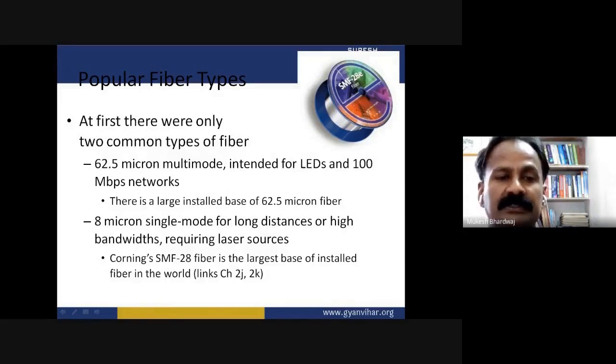There is a large installed base of 62.5 micron fiber. And 8 micron single mode for long distance or high bandwidths requiring laser sources. Corning SMF-28 fiber is the largest base of installed fiber in the world.